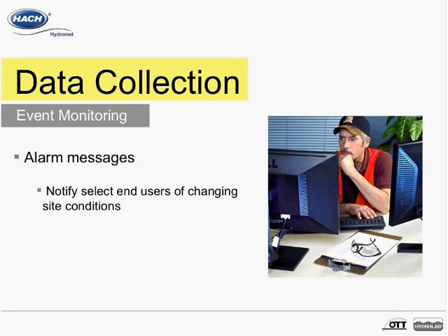For example, if your water level decreases by 2.5 feet from the last measured value, an alarm is triggered and an alert message is sent to predefined contacts to notify them of changes at the monitoring site. Notification of changing conditions at your site can help you determine if a field visit is required to grab samples or to service the site. Also, these alarms provide critical information to the necessary agencies or entities to make near real-time management decisions.